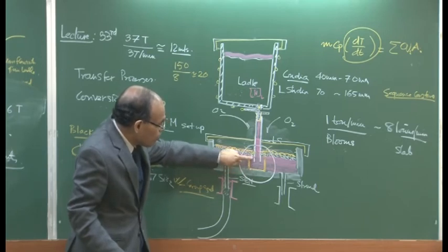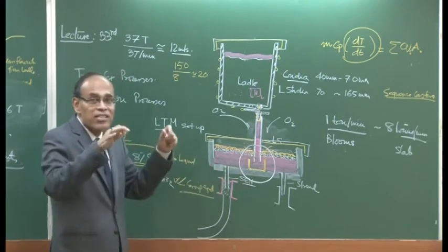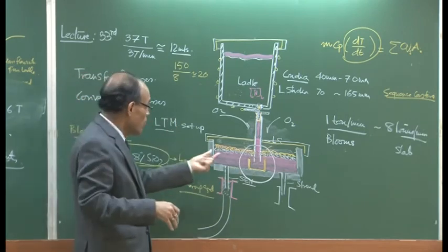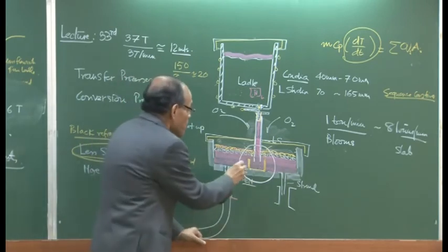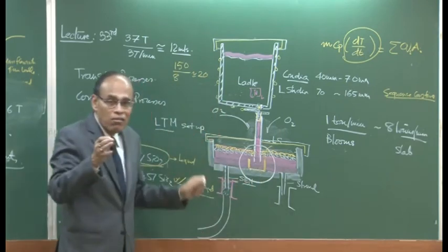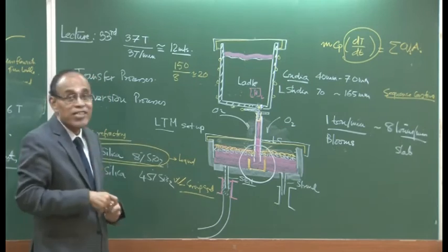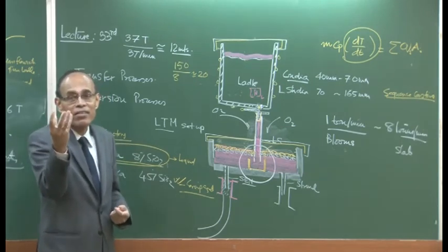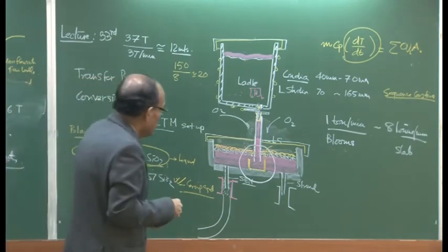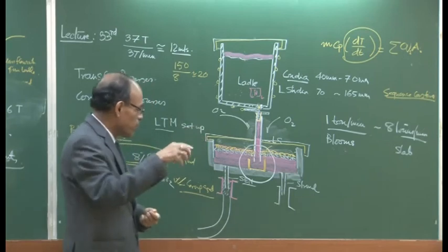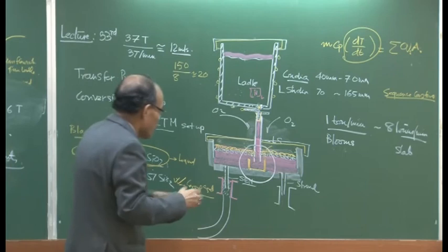In the process, the fluid is going to come in contact with solid. So the solid liquid frictional force is going to slow down the liquid, and as a result the intensity of turbulence, which is a function of the flow velocities, is going to be significantly dampened. There are designs available where the surfaces are serrated to create more surface area, just like golf balls are never smooth. Of course, the objective there is different, they want to destabilize the turbulence boundary layer.